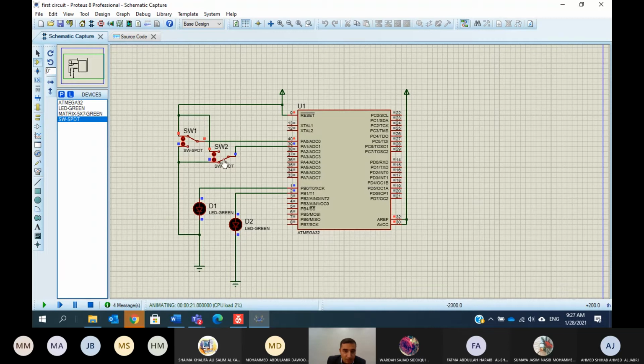The same applies for this port over here. Now you can see that the switches are working fine. VCC is working fine. The problem is with the output over here. Now let's start our double checking. The first mistake here is having two grounds. I will delete this ground and I will connect the circuit to the same ground. I will check again, still no output.